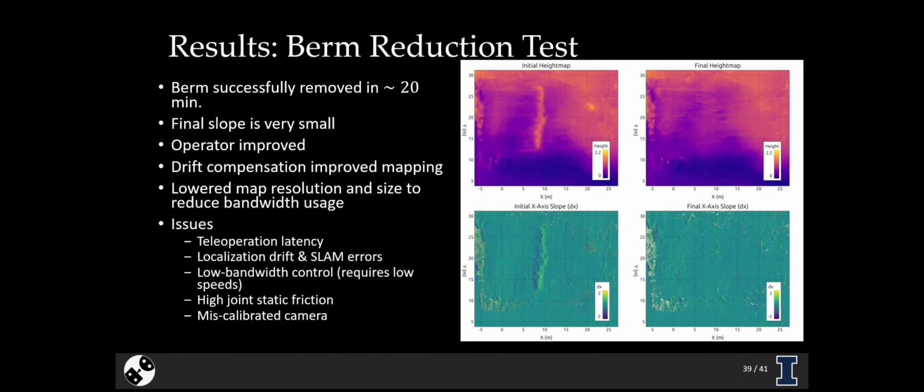These actuators, these valves themselves are very low bandwidth, coming off of the machine, something around 5 hertz. And additionally, the joints themselves are very high friction. So there's a lot of static friction, just the way that these couplings are made. And so this causes significant issues from a control perspective. And there's some latencies involved in the system as well.